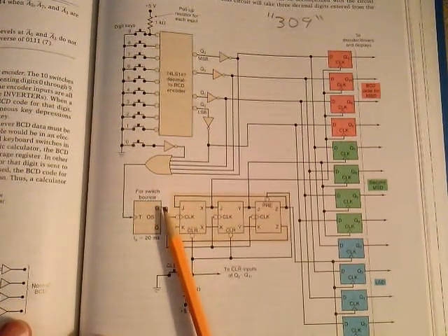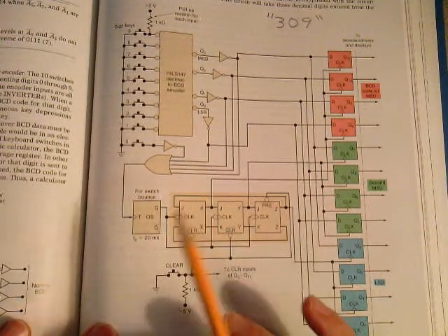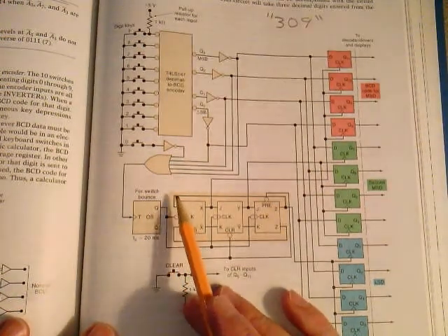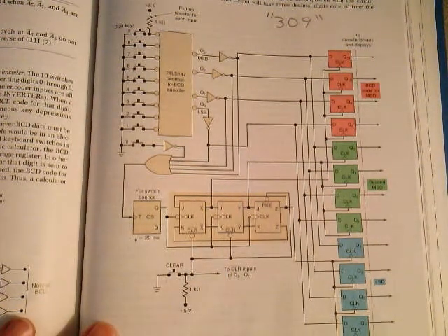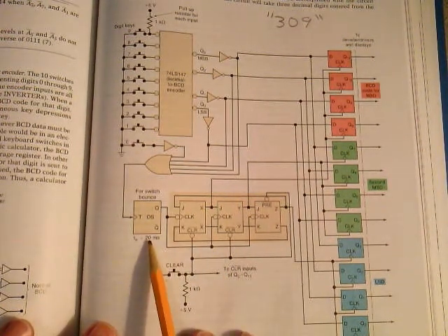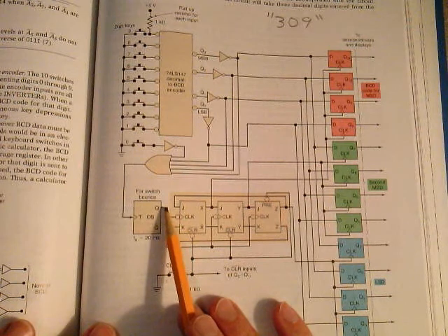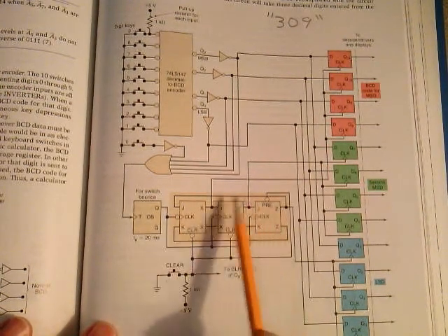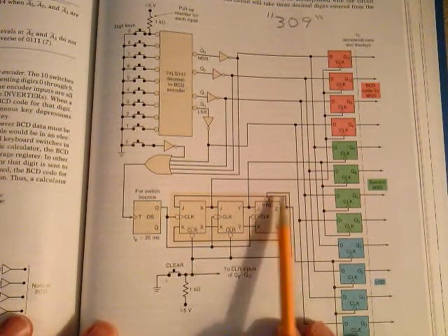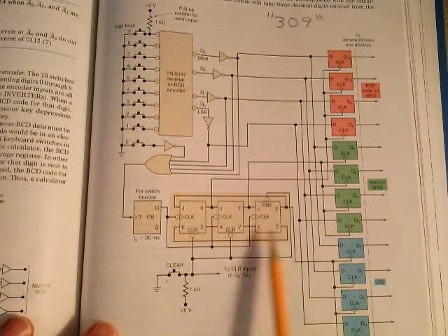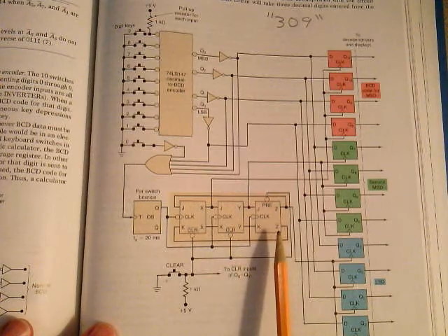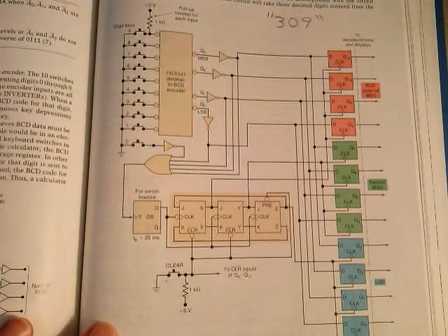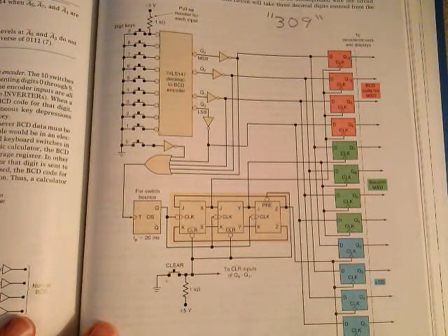This circuit here is normally going to be low, and then it shoots high for 20 milliseconds and goes low. It produces an output pulse for 20 milliseconds and goes back to its stable state, which is low. Notice we have JK flip-flops here. We're just going to use that as a ring counter. That's connected as a ring counter to generate different clocks. You'll see that in a minute. And we have a clear circuit, and here's our D flip-flops.